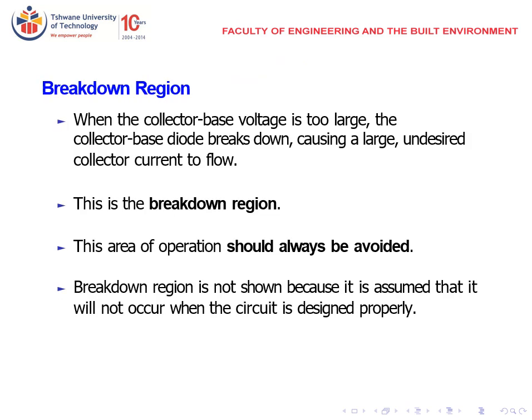The breakdown region. When the collector base voltage is too large, the collector base diode breaks down, causing a large undesirable collector current to flow. This is the breakdown region, and this area of operation should always be avoided. The breakdown region is not shown because it is assumed that it will not occur when the circuit is designed properly.